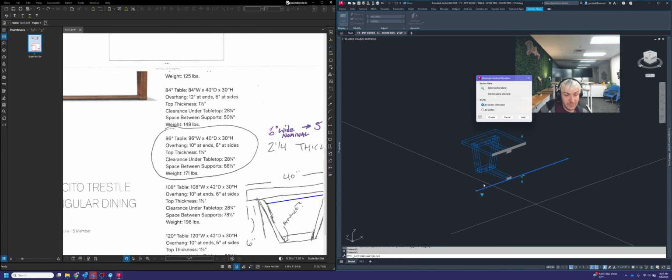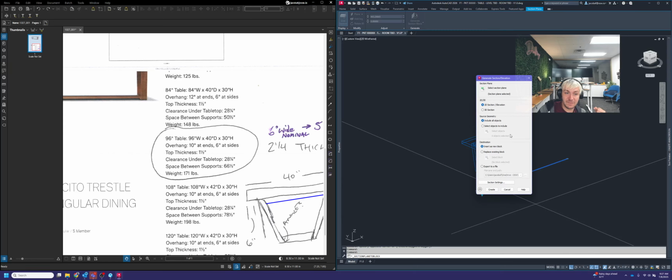All right, so again, kind of recapping what we've talked about. If you are in here for the very first time, it's going to look like this. There's not a lot going on. Just make sure that your 2D section / elevation object is selected. And then you're going to go down to this caret here to say show details. And this is going to get really complicated.